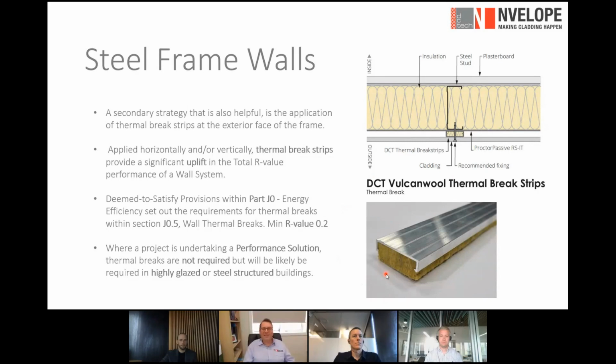However, when you start looking into the calculations, particularly around highly glazed buildings, or if you're using steel studs, when you start to model this, you'll find that you actually do need the thermal breaks, and unfortunately, you'll have to install them anyway. Well, fortunately for us.